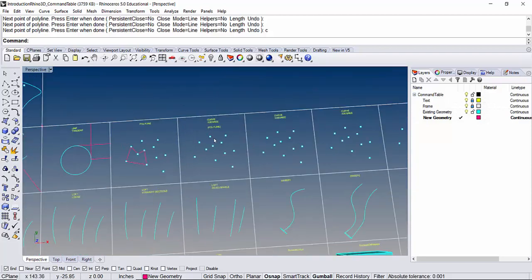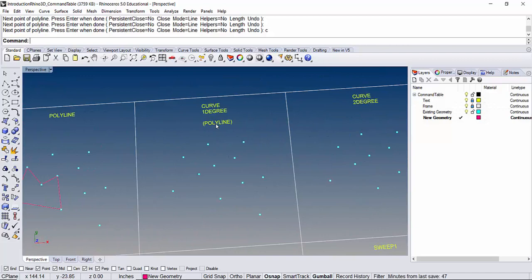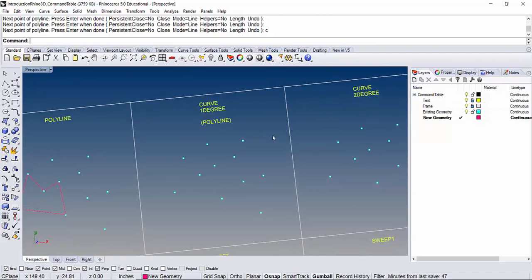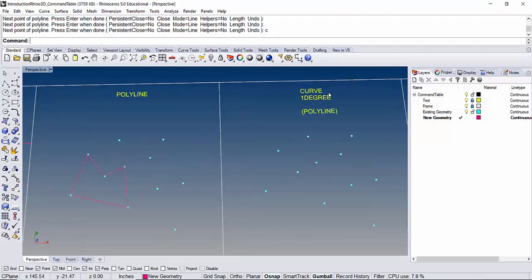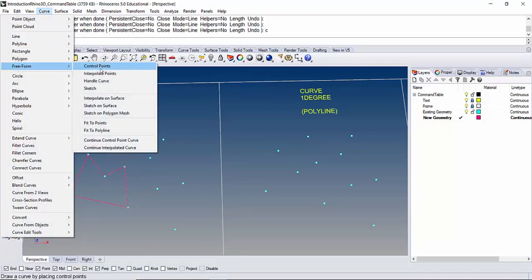All right, so this is where Rhino becomes interesting. Here we have a command called Polyline, and here we have a command called Curve. Yesterday, if you remember, we went to Curve under Freeform. We used the very first one, and I mentioned to make sure that your degree is set to 3. You remember that? Nobody really asked me why, and I said, well, we'll explain this later. So right now we're going to get to this concept of degrees in NURBS geometry.